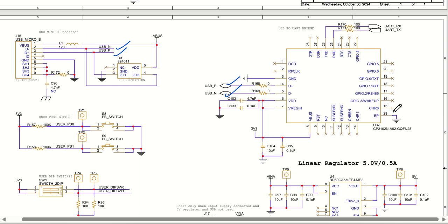What I have done is I have used one Silicon Labs USB to UART bridge. My UART pins will be coming, UART RX, UART TX from the microcontroller, and they will be converted to USB signal, and the USB signal will be directly communicating through our PCs. So this is how we will be communicating our UART signal to our personal laptops or something like that. This is a very simple circuit. I have not utilized a lot of other functionalities in this USB to UART bridge. It is just powered up with 3.3 volt, and it is simply acting as a UART to USB bridge.